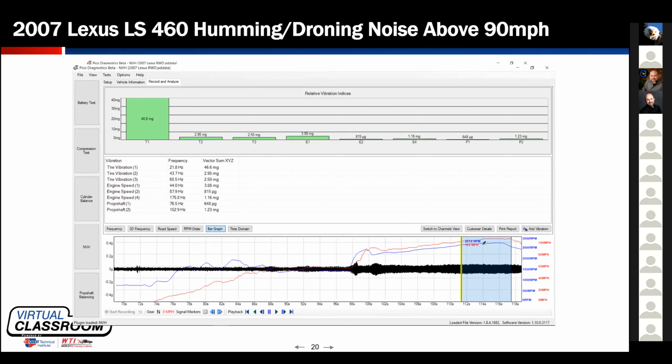Because think about this. Isn't it true that the carrier itself and the axle and the hub and the brake rotor, drum, wheel, and tire all spin at the same rate, which means it's telling me that I have a vibration producing this force once every time the tire goes around. So it could be tire, wheel, drum, rotor, axle, into the carrier. Now, come on, let's be logical about this. Driving the car, it hums or makes noises, you want to put a rear end in it.